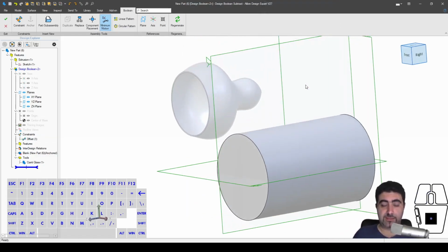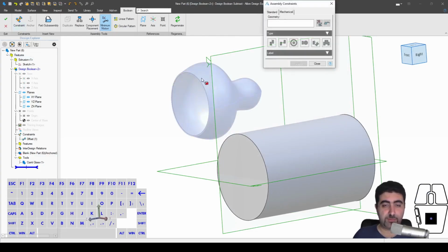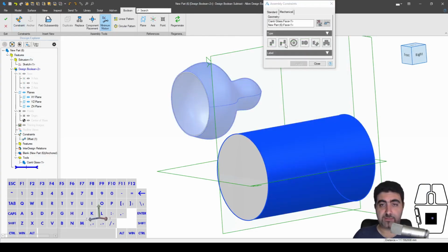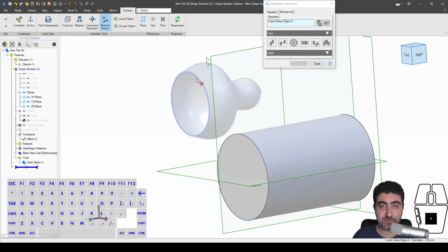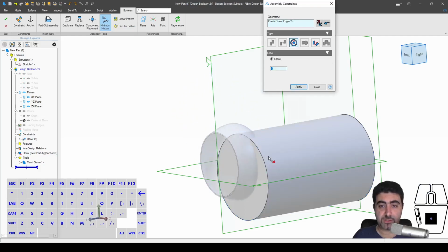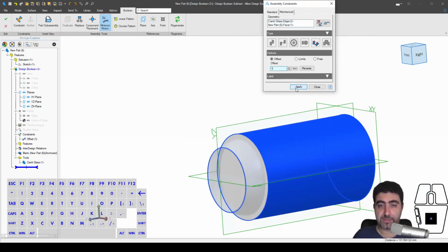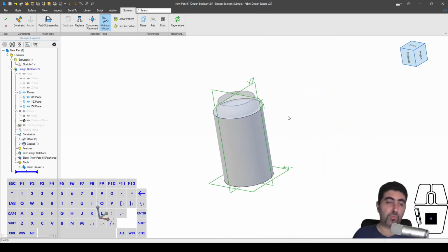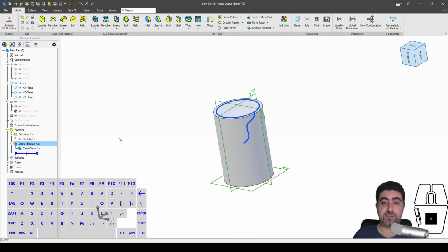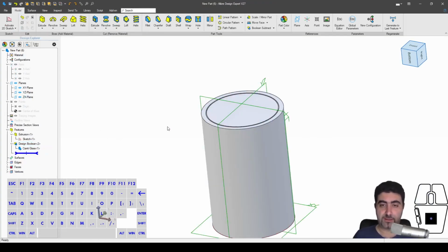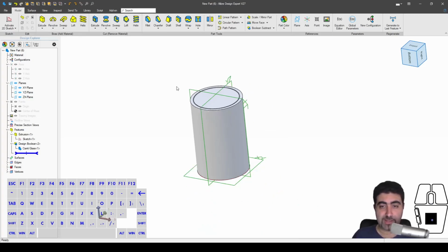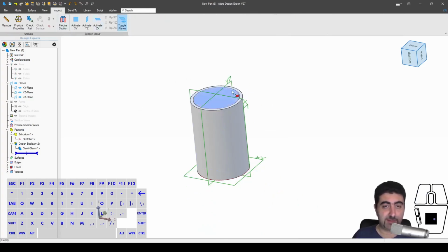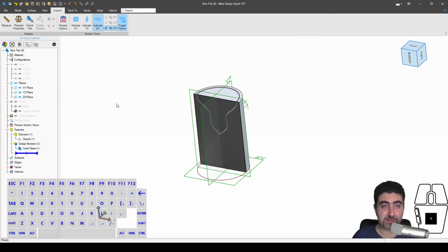Okay, so you do that, and then you just put one inside the other. Let's see if I can make the two. It's a spline, it doesn't understand that, but maybe if I catch this edge, yeah, now I get a coaxial. Okay, so what happens now? Well, I execute my Boolean subtract, and what has happened is, if I inspect it, so this is the ZX plane, I'll inspect it along the ZX, flip the section.